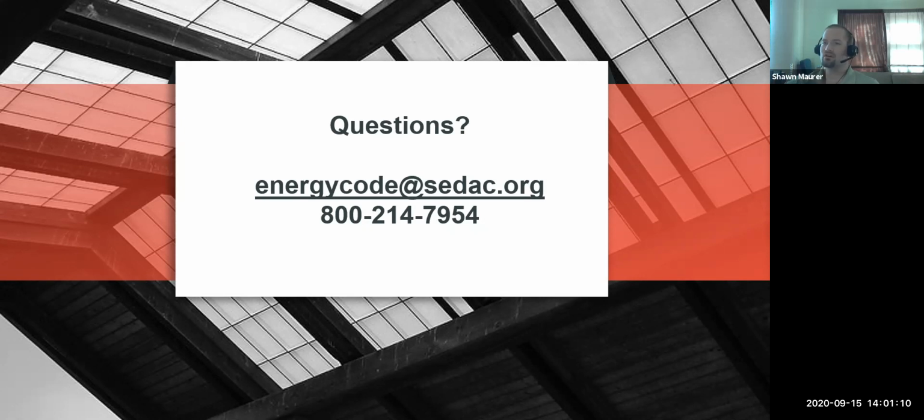Next question: does R402.3.2 require U-factor and solar heat gain to use an area weighted average, or merely permit it as an option other than using solar heat gain and U-factor for each window? It is an optional method. You can either use the area weighted average or you can use a prescriptive value for each individual unit.